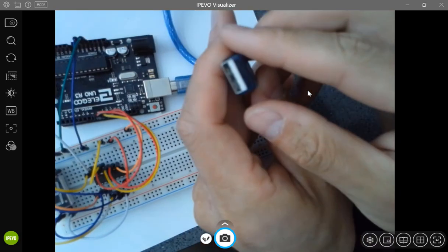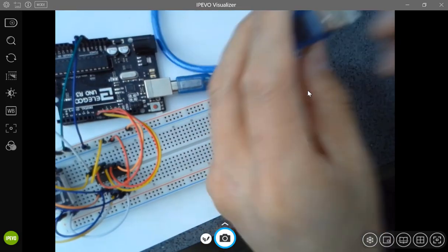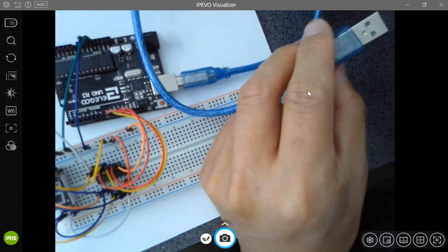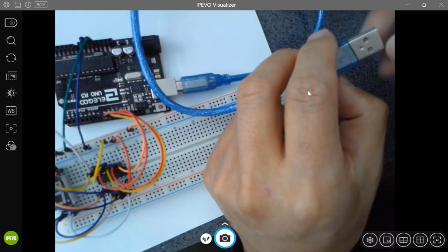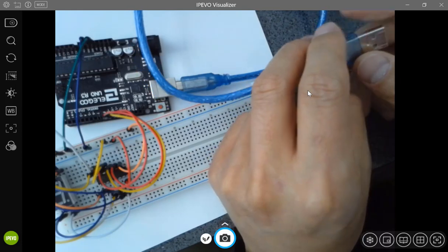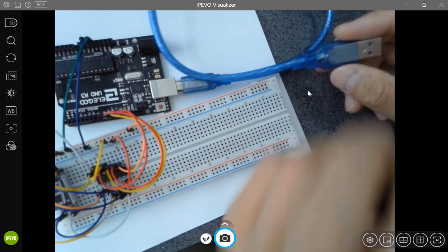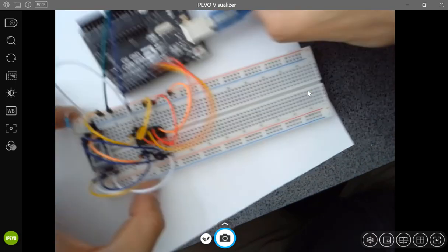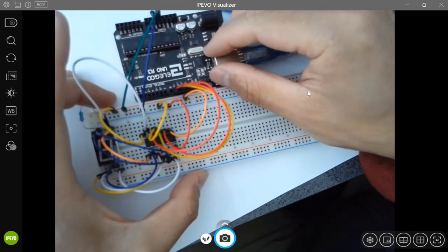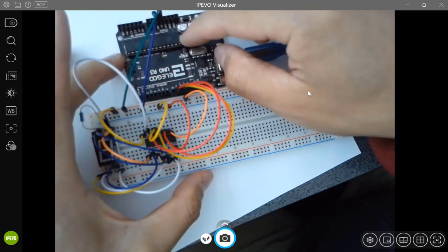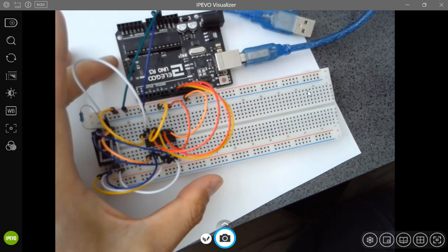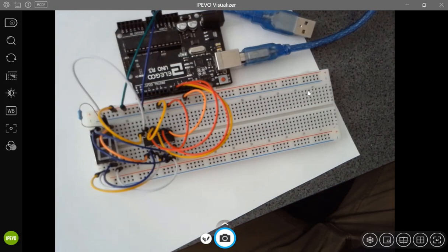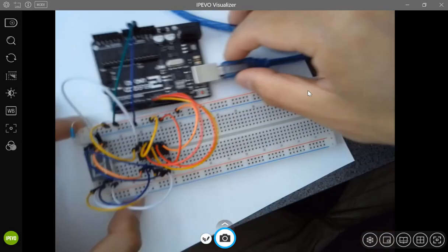Also the USB cord has a ground pin and a 5 volts pin. When I plug this into the USB port on the laptop, it connects the ground and 5 volts to my laptop. That's how you make the circuit. The 5 volts comes in and is directly connected to the serial pin of the chip. So all the logic levels are at the same level because they share the same common ground. 5 volts, 5 volts, 5 volts, like that. So that's how you power it up.